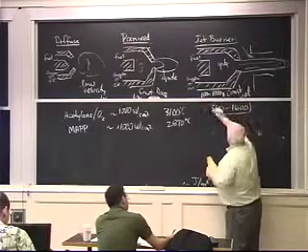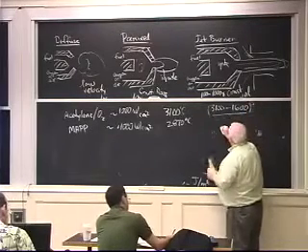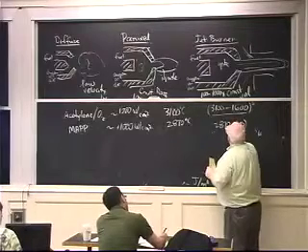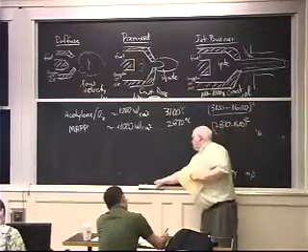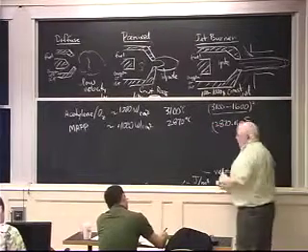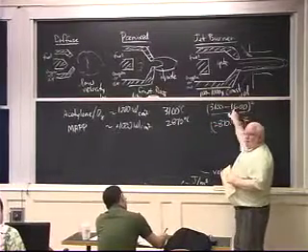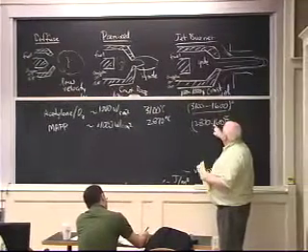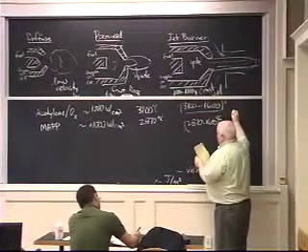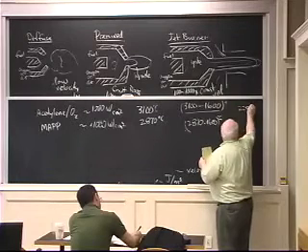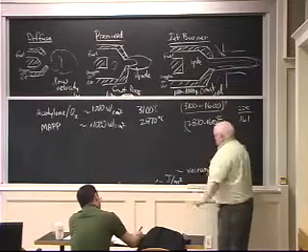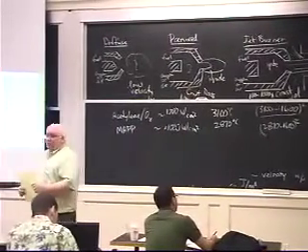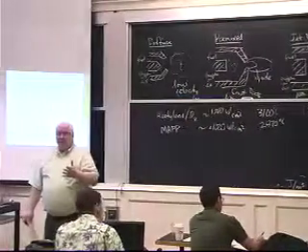And if I take that and square it, and I take 2870 minus 1600, and I square that, everyone see what I'm doing? This is just how much enthalpy I've got above the melting temperature of steel. So now I got to look at those differences and square those, and that works out to a ratio of 225 to 161. So acetylene is 50% more efficient than MAP for melting steel. Okay?